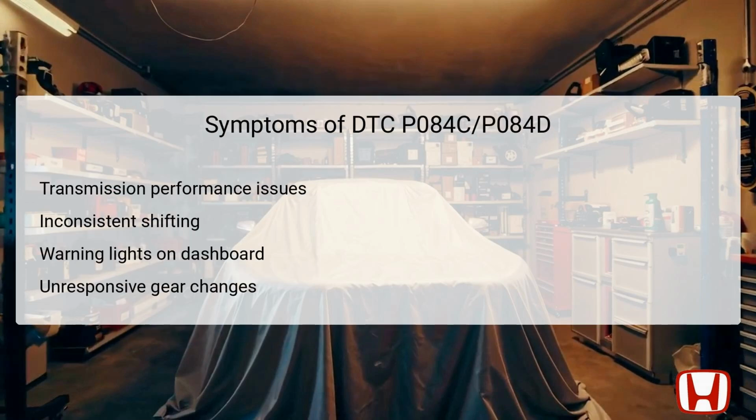When encountering either DTC P084C or P084D, several symptoms may manifest in the vehicle's operation. Drivers may notice transmission performance issues, where the vehicle may hesitate during gear changes or experience consistent shifting problems. Additionally, the dashboard warning lights may illuminate, indicating a need for immediate attention.